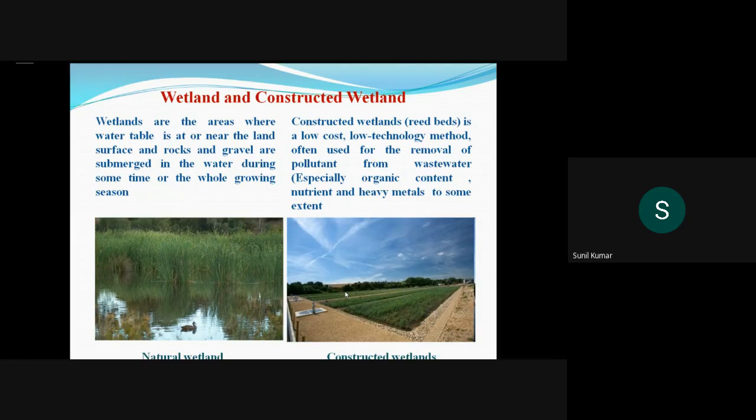It is required for the sequential batch reactor, activated sludge process or membrane bioreactor. In a membrane bioreactor, there are chances of breakage of the membrane, and sewage will enter into the final treated water. Those issues will be there. In a sequential batch reactor also, you have to maintain the dissolved oxygen content and recirculation, all those things. Here nothing is required. It is only a once-through process.